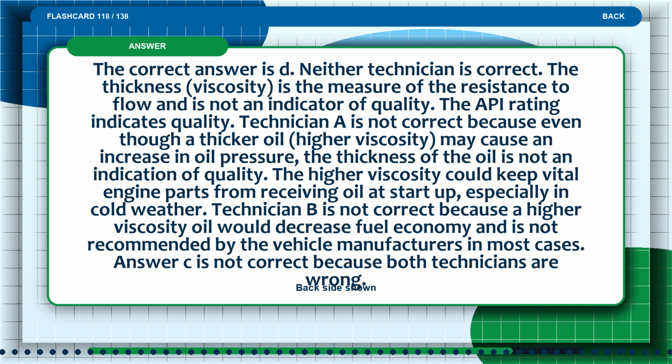Technician B is not correct because a higher viscosity oil would decrease fuel economy and is not recommended by the vehicle manufacturers in most cases. Answer C is not correct because both technicians are wrong.